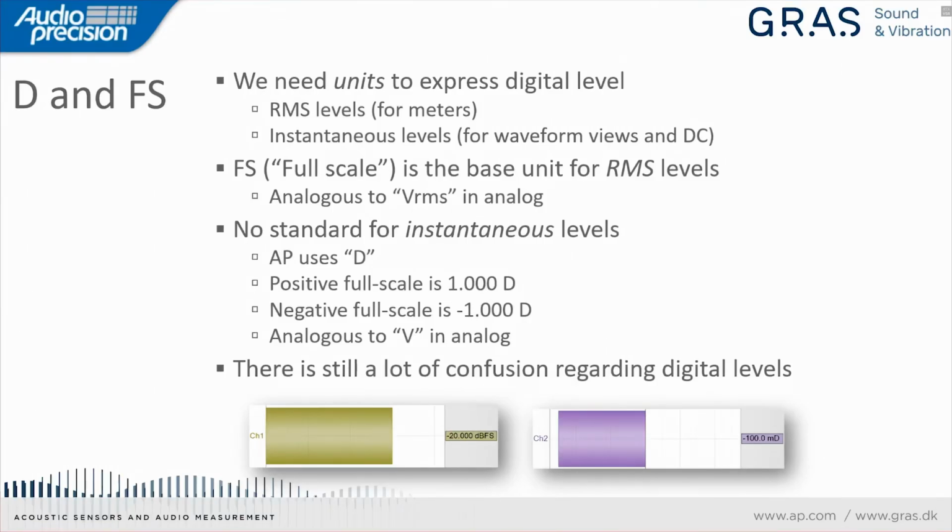So what's actually going on behind the scenes inside of an APX analyzer is up to 192 kilohertz sample rate, or roughly 90 kilohertz bandwidth, we're using one set of analog to digital converters. And then to go to the next step in bandwidth, we actually go to a completely different converter that operates at a much higher sample rate. So that's why there's that sort of step function, is that there's internally to the APX555 a gear change.